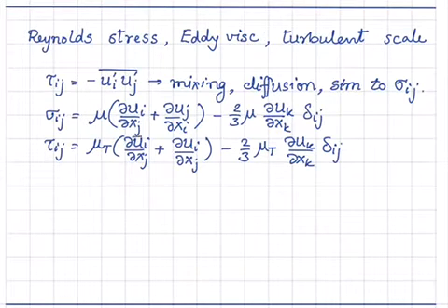Now these are defined in terms of mean velocity, u bar everywhere, which means that if you're computing the Reynolds averaged Navier-Stokes equation to get the mean flow, these u bar and the derivatives will be known as part of the solution. So we can compute tau ij if we know the eddy viscosity mu t. So from 6 or 9 tau ij's which were unknown, now we're down to one quantity, which is mu t, eddy viscosity.